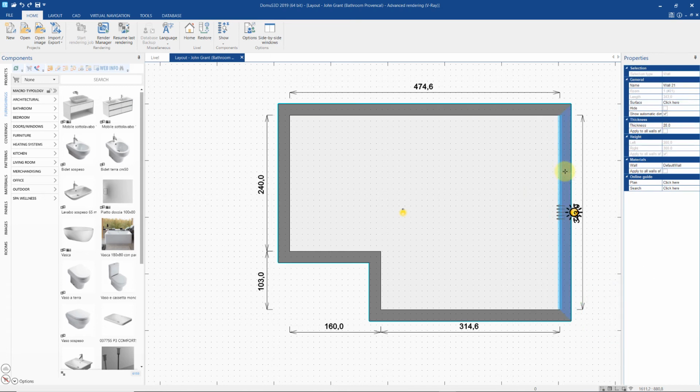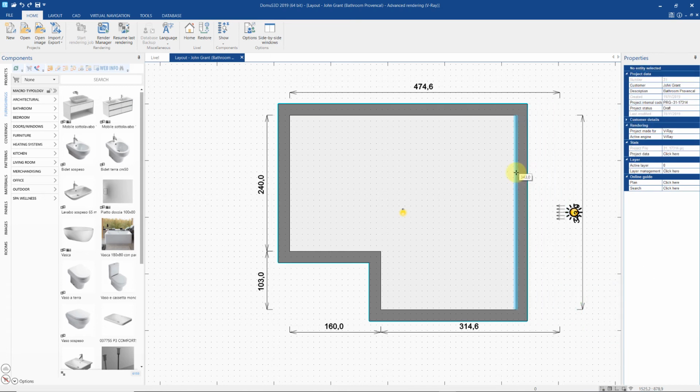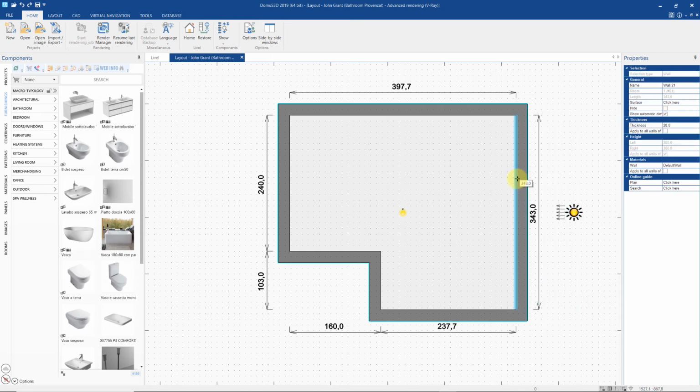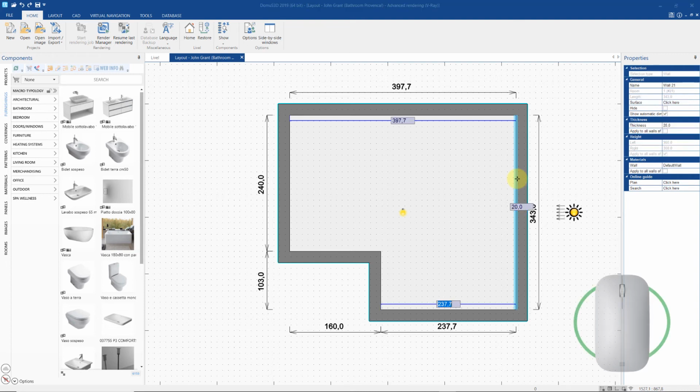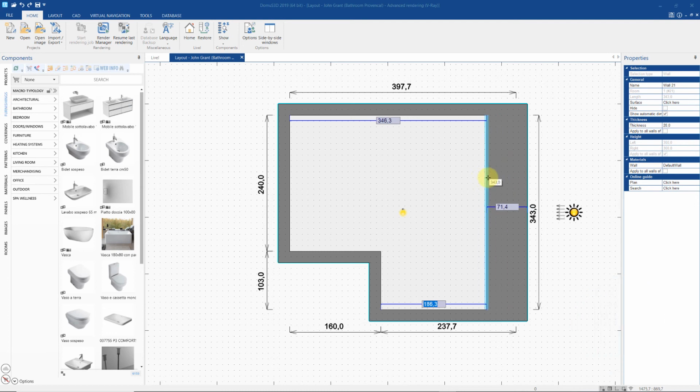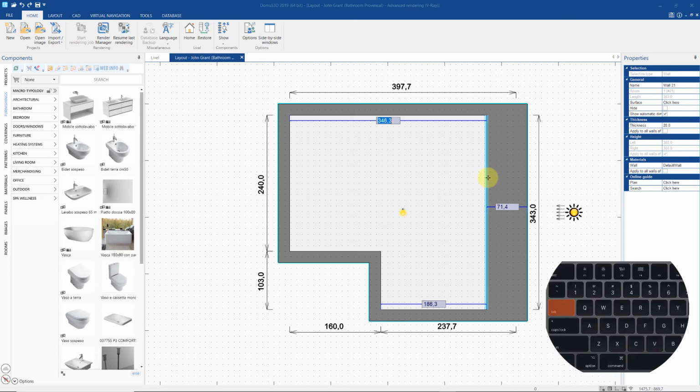If we instead click on one of the wall surfaces, we can drag it in order to change the width, although it's hard to get a precise measurement since we don't currently have any dimensions showing to help us. After we click to select a wall, if we click again, we'll call up the dimensions so we can be as precise as we like, writing exact measurements for both the width and the distance to other angles in the room. To move from one field to another, we hit the Tab key on the keyboard.